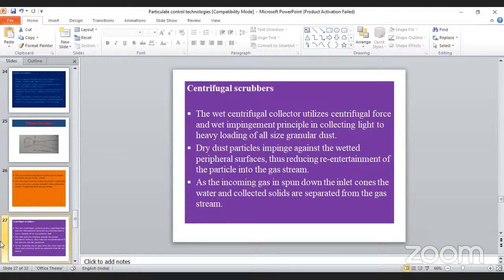How are we reducing the horizontal velocity or flow here? Look at the diagram where the inlet is, one narrow section is there, and again the wider path is there. When the inlet is a little wider, the section is very narrow, and again the flow path is highly wider. So when we provide the high horizontal surface area, automatically the flow will be reduced, and the horizontal velocity also will be reduced.